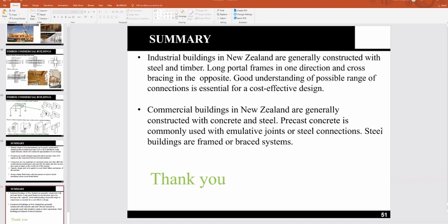For high-rise structures, we use high-grade materials, which are usually brittle. How can we overcome the brittleness with ductility? That's a very good one. If you look at the stress-strain curve of concrete, as the grade of concrete increases, the ultimate compression strain reduces. So what you need to do is detail such that the reduced compression strain limit doesn't get reached. It's a part of the design.